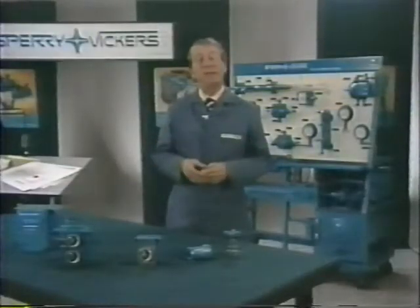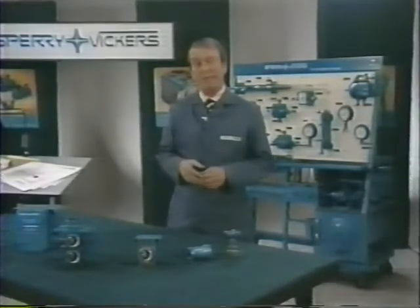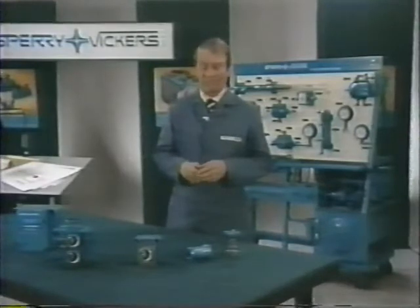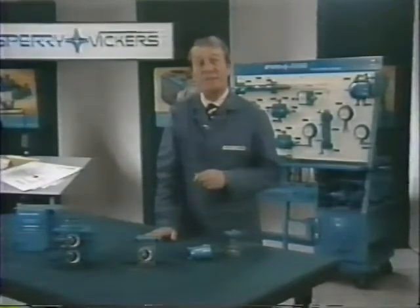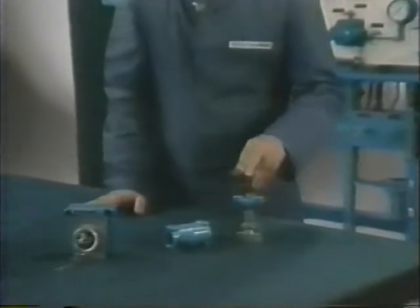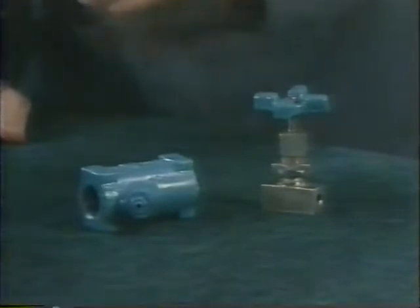So, there are really 3 possible locations for the flow control. Where it's located is determined by the requirements of the particular application. Well, we've spent a lot of time on theory and schematics. Now, here's the actual hardware. Here again is our simple needle valve. This one's a non-compensated flow control. It's adjustable, and it has a check valve built into it for reverse free flow.